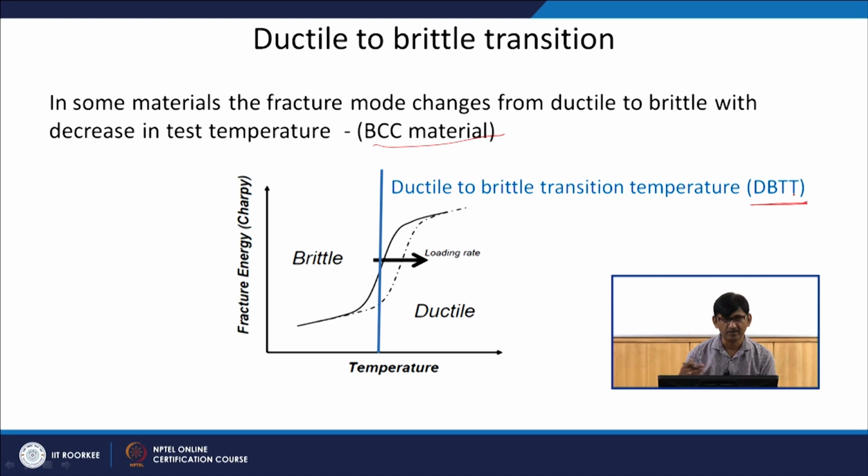When you develop a new material, you have to do testing at room temperature, high temperature, and low temperature, under different loading conditions. Static or quasi static loading means a very slow strain rate, and high strain rate testing we call impact. Depending upon the application, if it is not going to see any high temperature, we will not do any high temperature testing of that.